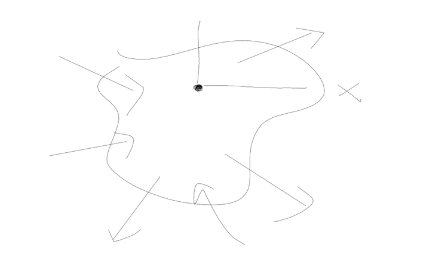So that brings me back to that general case. If I have a situation where I have some weird, random structure, and there are forces being applied in all directions, and I take a point on this structure and I want to know what the stresses are at this point, how do I determine that? Well, it now becomes pretty arbitrary how I set up my coordinate system. I could choose that to be the x-axis, that to be the y-axis, that to be the z-axis, or I could choose any coordinate system that I want. And what that means is I'm going to have a bunch of different stress values. So this is what we call a general state of stress in mechanics of materials.